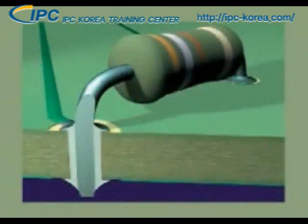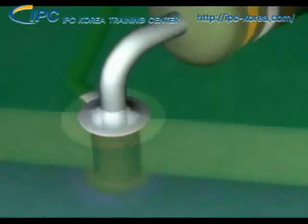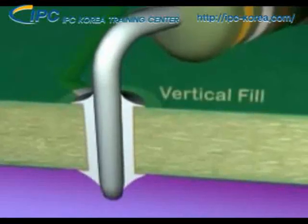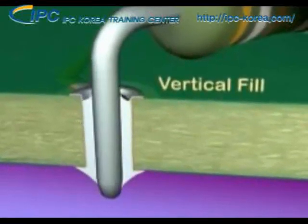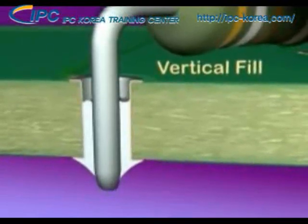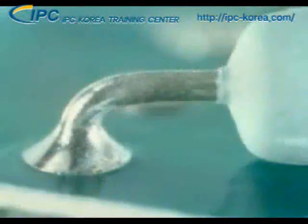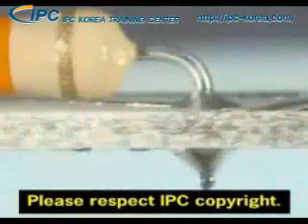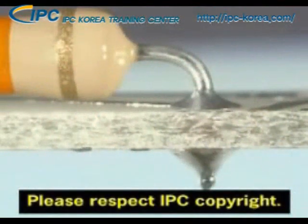Now let's examine the acceptance requirements for the barrel of the solder joint. The first requirement we'll examine is the vertical fill of solder inside the plated through-hole. To evaluate this condition, you must look at the solder joint from both the component and the solder sides. While we've seen that the ideal or target connection has a slightly concave, cone-shaped fillet that rises from the outer edge of the land to the component lead, the solder joints you see every day may not always live up to this ideal.